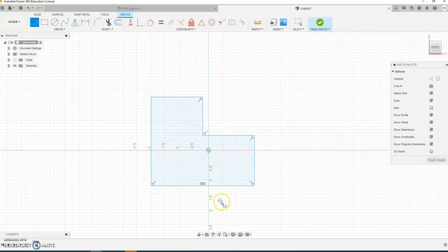All right, so there's my great L-shaped block. Now notice, here I have the perpendicular symbol showing it in the corner, and I have the parallel symbol here that shows that it is parallel to this origin x coordinate. I had this problem a few days ago, where somebody had made a mistake and their drawing would twist. They had it fully dimensioned, and they had it fully constrained, they thought, for the midpoints of their lines, but yet their drawing still wasn't black.